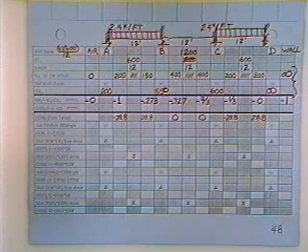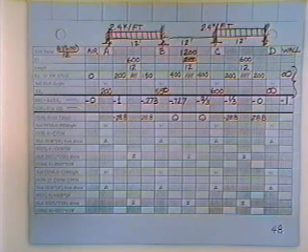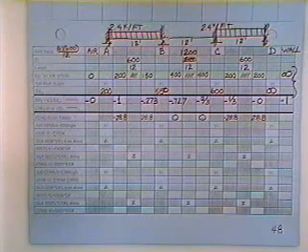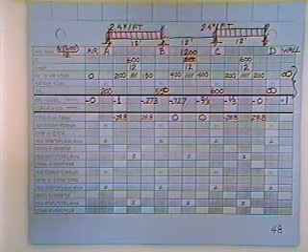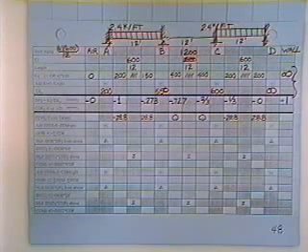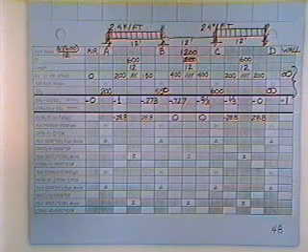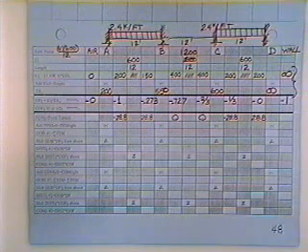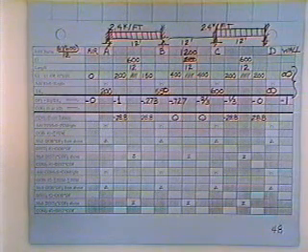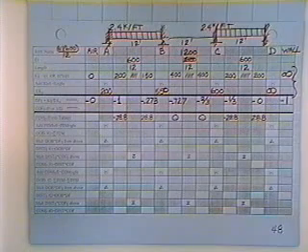But basically, I'm reading from the top of page 45, a carryover factor is 0 if you're going to a member that on the far end is pinned and quits. In other words, there's no more members. The carryover factor is a half if there is another member down the road, or if there's a wall. If there's anything down on the other end, the carryover factor is a half.